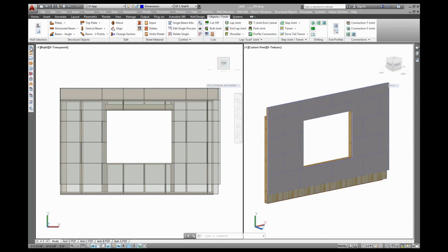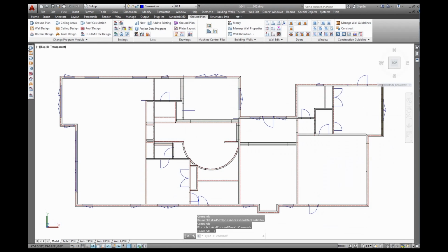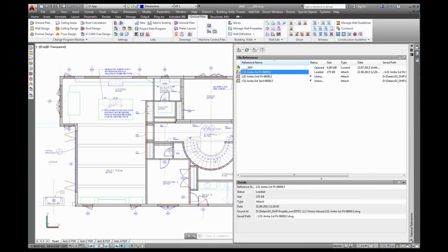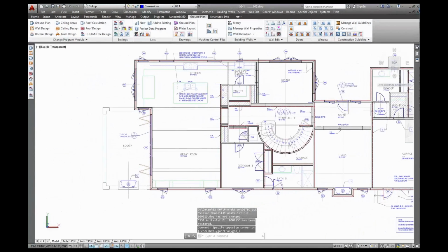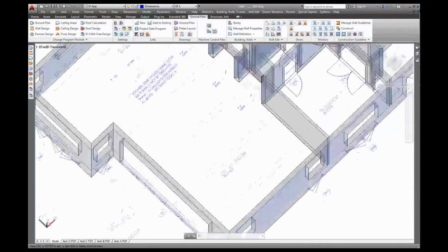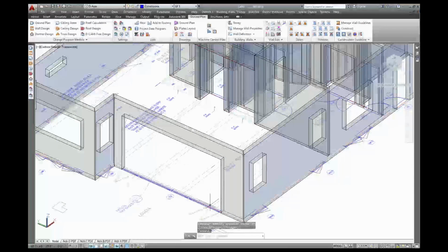If I go back to the floor plan now, I can show you why it is essential to have a 3D model. I'm just going to bring in the floor plan from the architect again. And over here in the great room, there's a couple of big floor joists. Those are going to be visible afterwards. And they're bearing on 2 walls. And on this wall here, we have a huge, big opening, bifold doors. Very nice, but our floor joists have nothing to bear on.